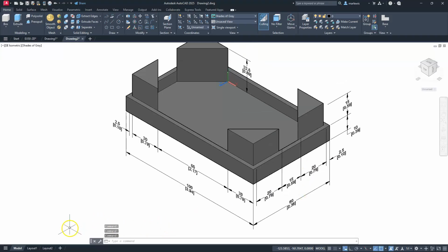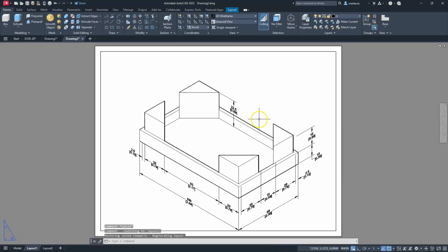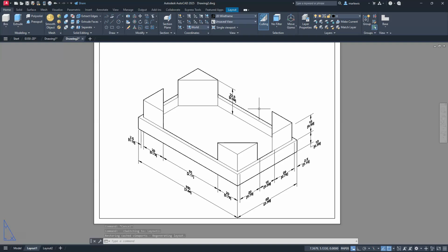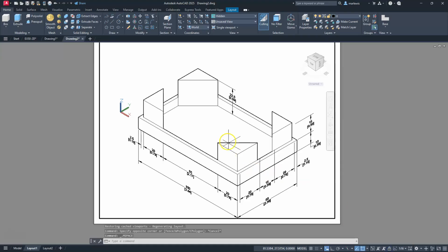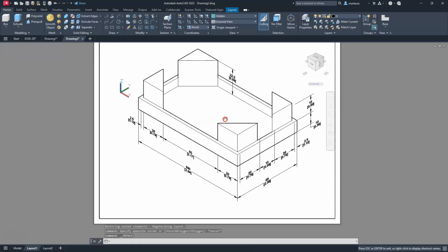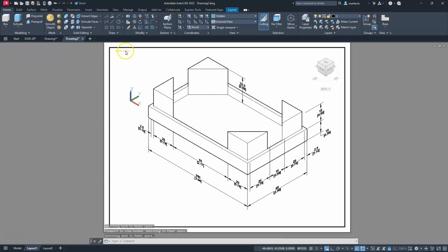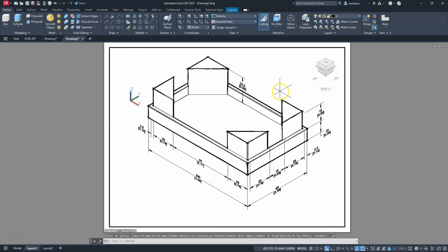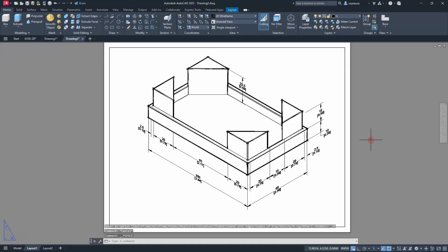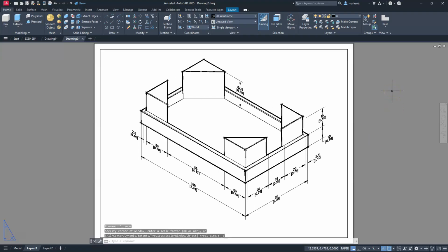Let's go ahead and take a look back in the Layout tab and see how this looks. All right. And you can see that I do need to pan this up a little bit, or move it around. So I will double click here. I'm going to unlock it, and I'm just going to use the pan. Try your best not to scroll, or make sure that this number stays 16. Then I will lock it again. And then you can play with the view how you want this to look. So remember that it will print out whatever view that you place this as. So if you do like something to look like this in a sketchy look, by all means, go ahead and do that, right? So this should hopefully conclude another one of these videos.